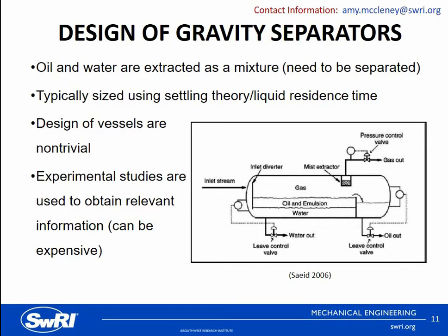While separators are used in all sectors, reliable separation is especially important to the economic viability of remote location resources in difficult applications, such as heavy oil, produced water, and sand disposal. Separators are composed of large vessels with complex internals to promote coalescence of liquid droplets and eliminate mist from gas. Design of multiphase separators is a non-trivial task, requiring complex separation physics and knowledge of fluid properties, flow rates, and inlet mixing conditions. Proper sizing has historically been strongly dependent on data collected at field-like conditions.